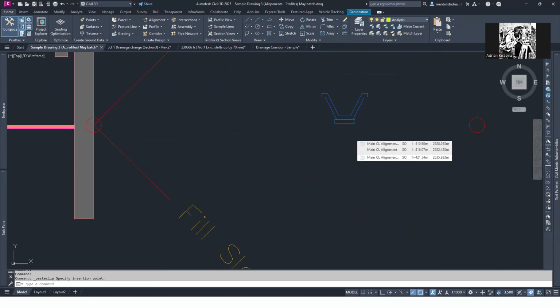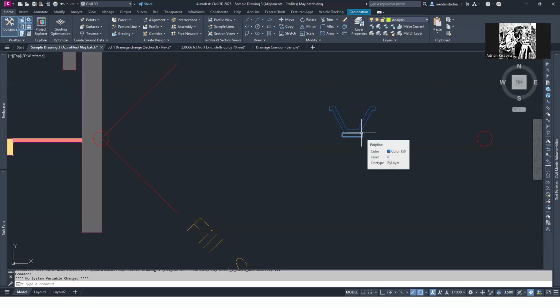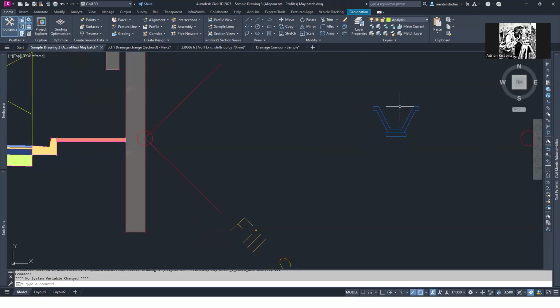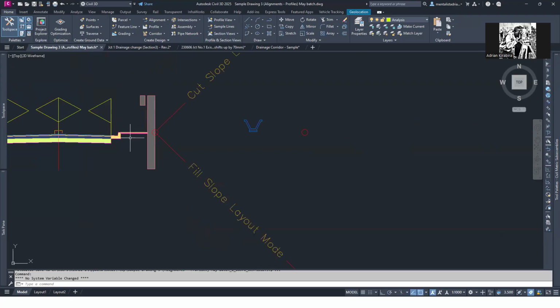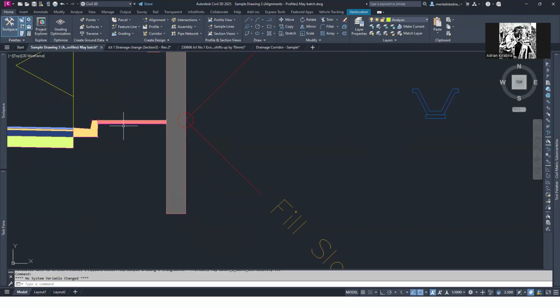What I'm saying is you need to get the feature that you're going to transform into the sub-assembly with the correct dimensions and the orientation. Now, you put it beside where you're going to put your assembly.